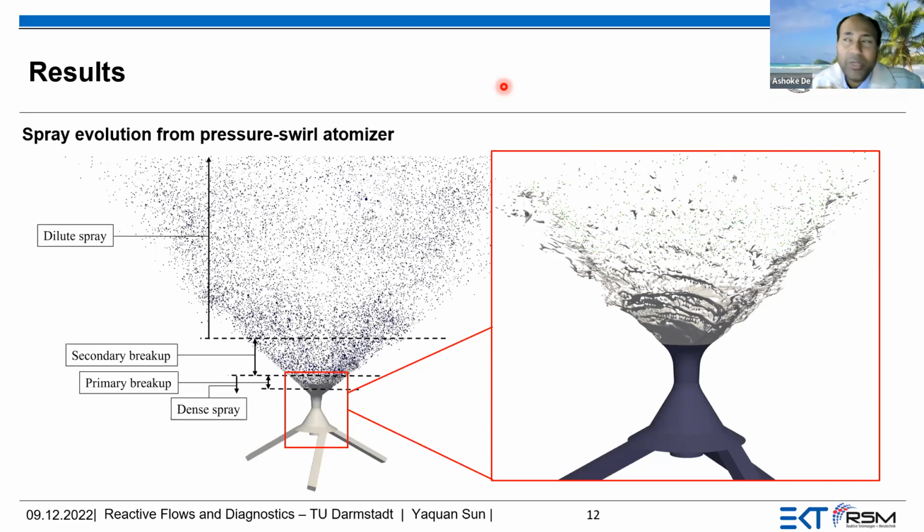Yeah, I mean, another way is that we may have separate tables for boron particle oxidation and the second phase hydrocarbon. Two different kinds of tabulations we can do, not a single tabulation. But somewhere inside the main program, we have to make the connectivity, because you will get temperature from both places. So it has to be some sort of a mixture-weighted approach. One can do it this way, but I think it will be huge. Yes, it would be huge. If you combine both, I think it is easier to follow. That's true. I think following the path that we use for coal combustion is better.